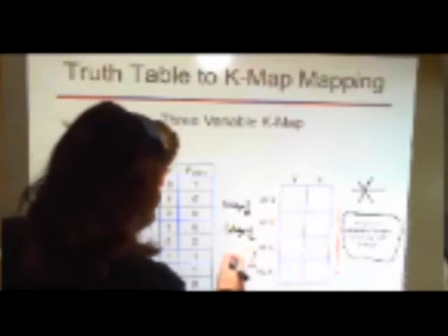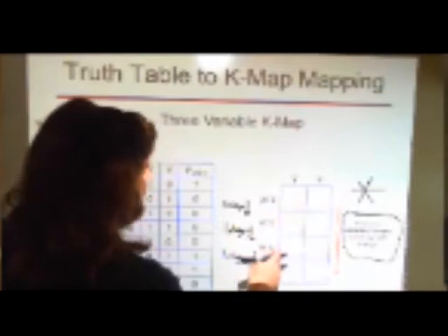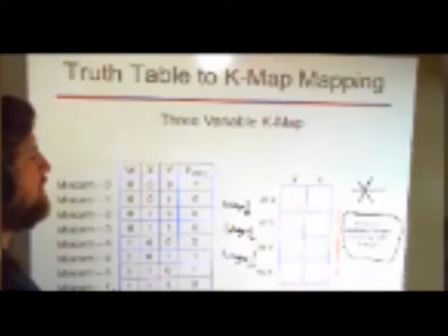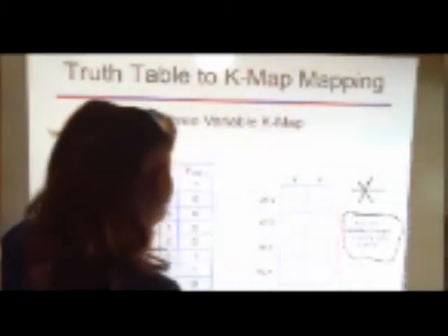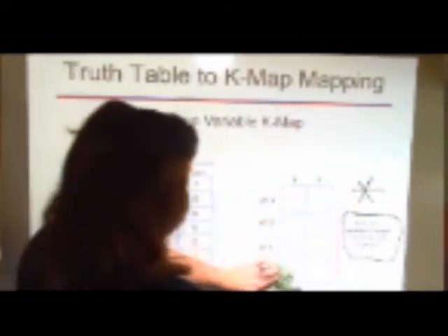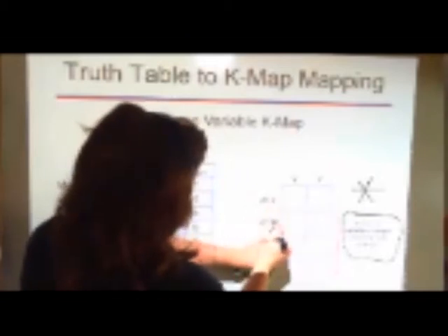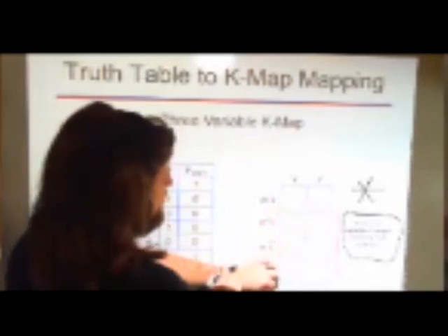When we go to the next one, it's still only one change because we went from WX to WX naught. Now I'll point out, if we had this table and instead of what is correct right here, we had what is the common thing I see students do that is incorrect: they'll have W naught X naught, they go W naught X, and then they want to do WX naught because that's like the flip of it.